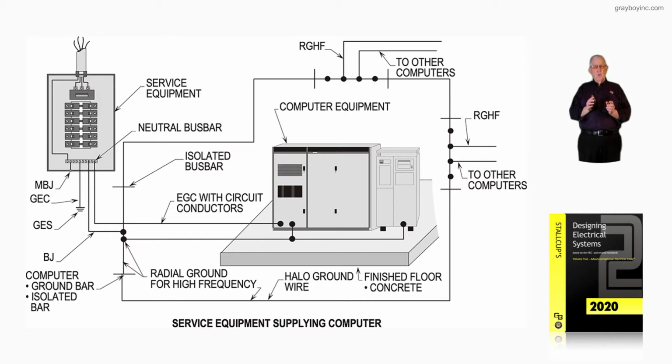But now if you're in a computer room and the room meets the definition of a computer room, then 645.15 would rule. And then notice we could use the raised floor, the metal of the raised floor, bond all the enclosures of the sensitive electronic equipment to such framework. Or we could build an equal potential plane by using number 4 conductors stripped and put on 2-foot centers. You know, they did that in the past.